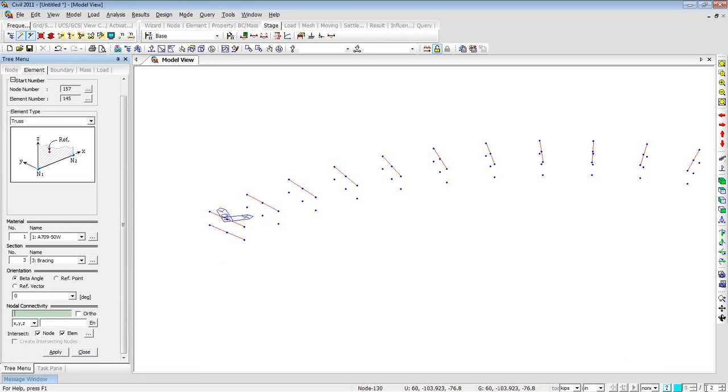Now if you see at the corner of this screen, on my right hand corner, you will see a number 2 written there. This means the program will automatically snap a node at the midpoint, or divide one element into two pieces. If you want to have the element divided into three pieces, you can have this number as 3, 4, 5, and so on and so forth.